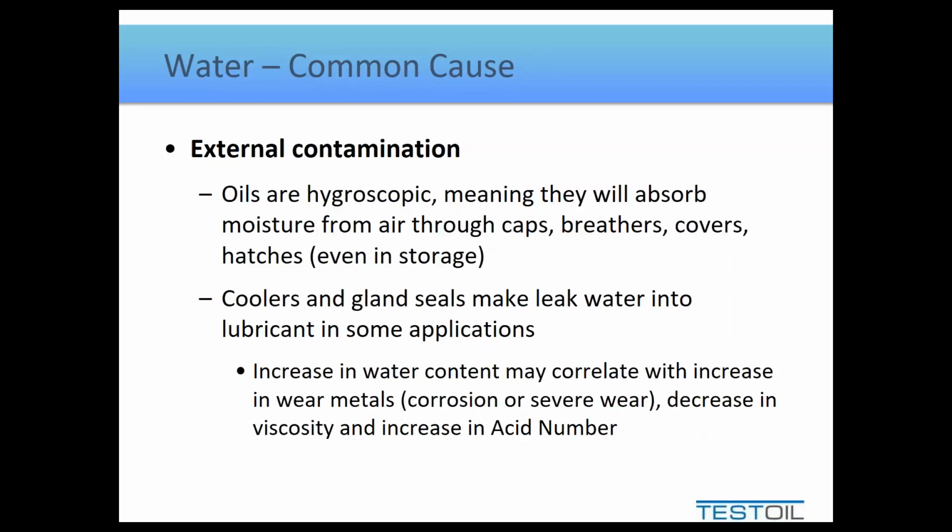Another source of water, though, is if we know we have a cooling system. Generally speaking, we use a water-based fluid on one side and we'll have our lubricant on the other side. If any of those cooling tubes begin to leak, or if any seals in between both systems begin to fail, then water, of course, will migrate over to the oil side.